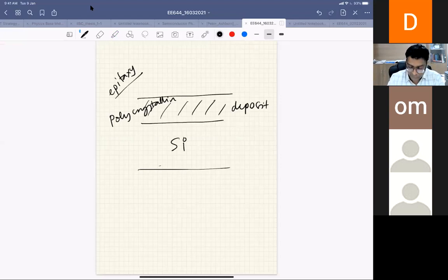Yes. So at the junction of polysilicon and silicon of the emitter layer, there would be some defects. So that wouldn't cause any problem during the operation of the emitter. Yeah, there will be defects, but that is not an issue. There will be some interface, but that is not an issue. That is inside the emitter, right?